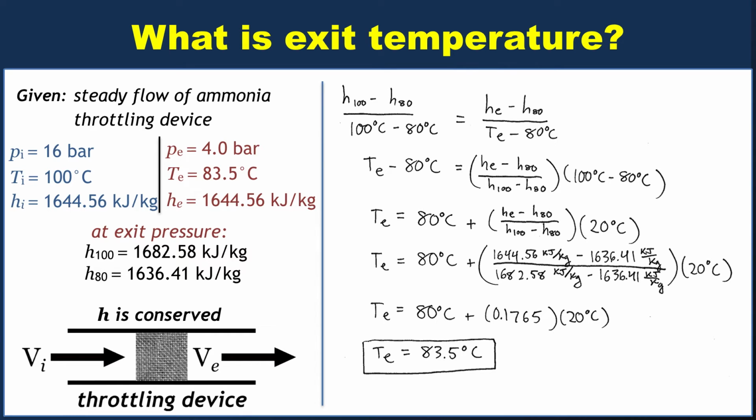If you try doing the same problem with the NIST website, you'll actually get about the same answer, but with different numbers, which is a little weird. A few students asked me about differences between the NIST website and the back of the book. This is one that I wasn't aware of, but discovered, namely that it doesn't always list the same values of the specific enthalpy. The nice thing is, though, it does list corresponding differences correctly. So what they're probably doing is using a different 0 point for the internal energy. There are complicated details having to do with that choice, but for our purposes, the important thing is that you get the same answer when you do the same problem.